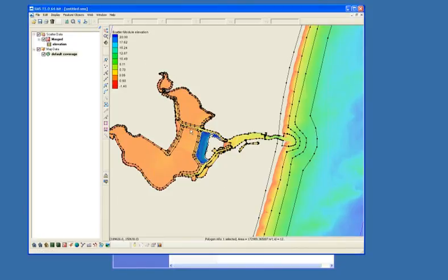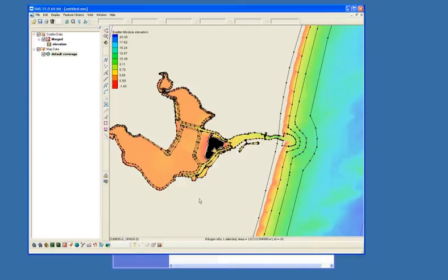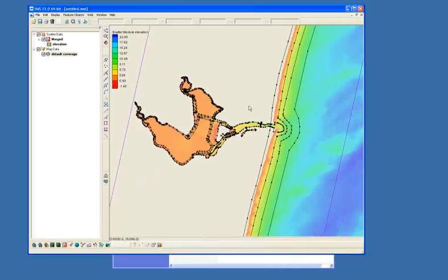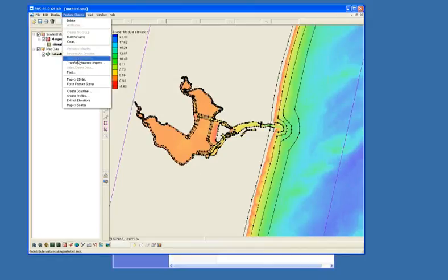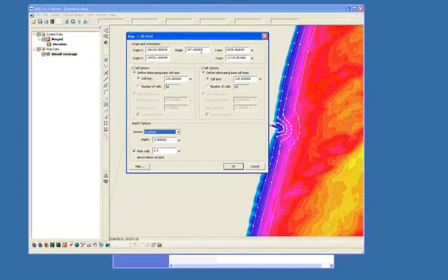You can specify some of these to be, rather than giving a telescoping size, you can say it's not going to be ocean at all, it's actually land. And then when you build the grid in just a few minutes, it will choose that arc and create land cells inside of that. So we can do this real quick. Assuming we've set all of these appropriately, we can go under Feature Objects, Map to 2D Grid, exactly like we did yesterday with the variable space.